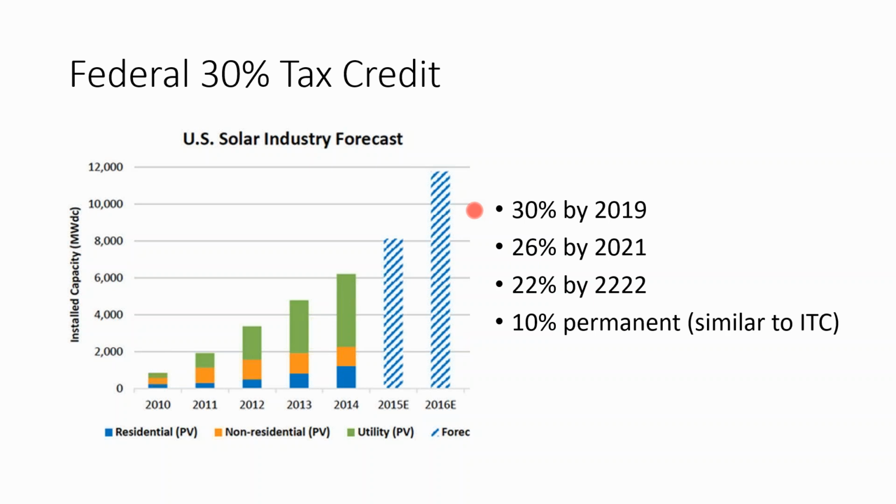Because if the solar is reducing your demand at peak times and your battery is running during peak times, the question is, well, do you have enough solar power to charge the battery back up, if your battery's running in the morning, and do you have enough surplus in the middle of the day when you also need demand reduction and the solar array is taking over? Do you have excess in addition to that to charge the battery back up so that the battery can be used in the evening?